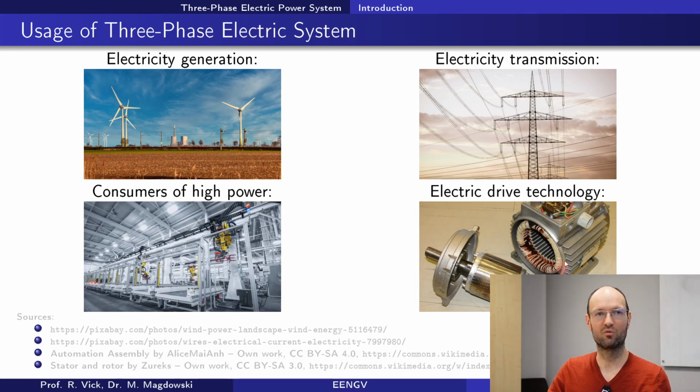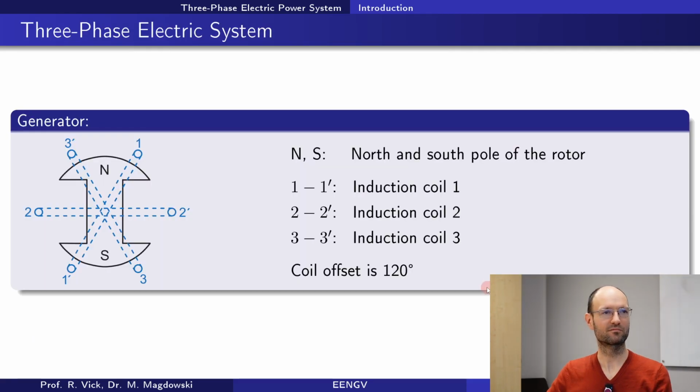The outer field would always rotate with the same speed as our mains grid, and then in these asynchronous motors there is some field induced in the rotor, and you need to have the slip, you need to have the difference for this induction. And so they will rotate slightly slower, maybe 2% less, 5% less, something like this. But yeah, this is what we will talk about in other lectures.